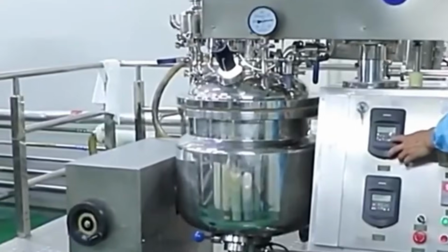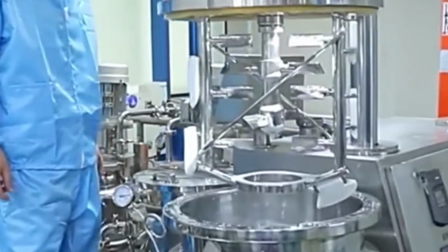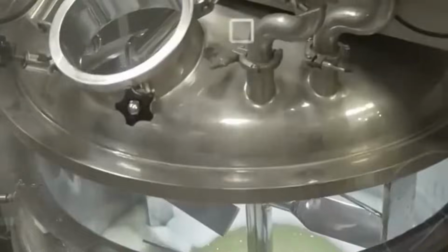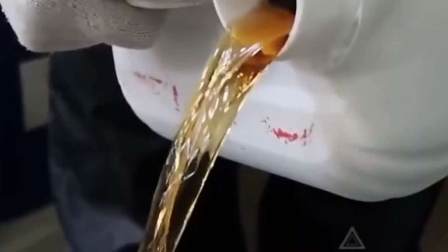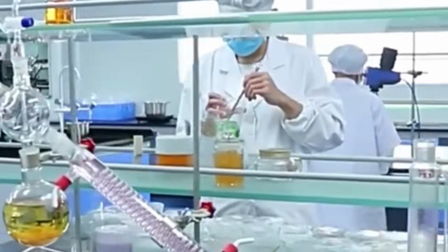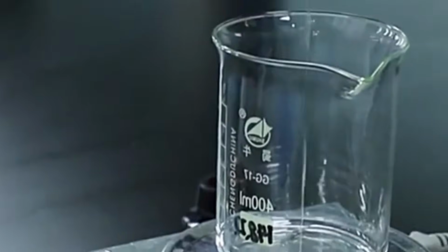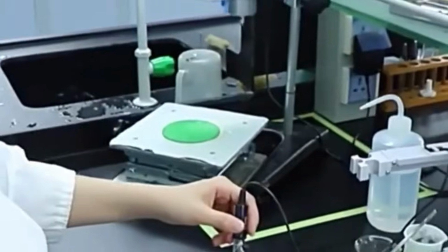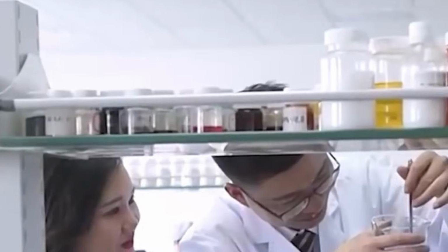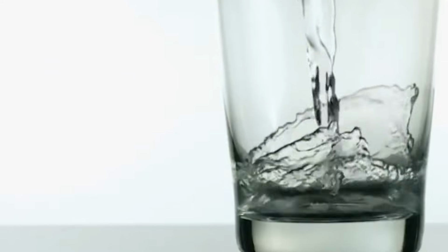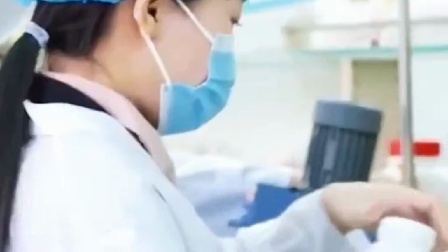Fragrance is added near the end of the mixing process. Fragrance oils are complex blends of aromatic compounds and are typically pre-dissolved in a solubilizer or surfactant base before addition. This prevents separation or clouding. Fragrance addition is carried out under low agitation to minimize volatilization and foaming. Dosing is controlled with high accuracy peristaltic pumps due to the low inclusion rate.